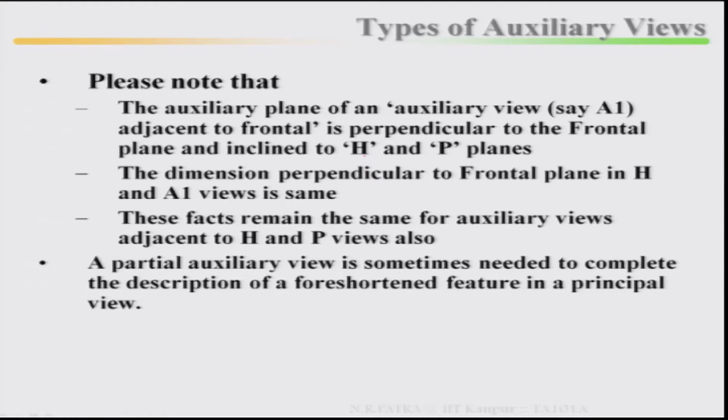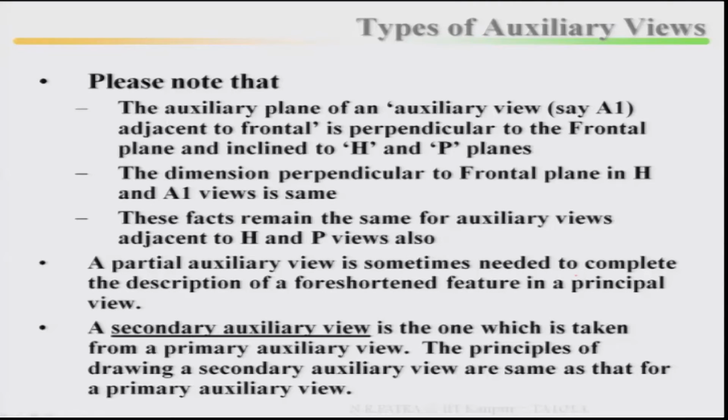A partial auxiliary view is sometimes needed to complete the description of a certain feature in a principal view. Remember this point: not necessarily a complete auxiliary view, a partial auxiliary view is sometimes needed to complete the description of a certain feature in a principal view. A secondary auxiliary view is one which is taken from a primary auxiliary view. The principles of drawing a secondary auxiliary view are the same as those for a primary auxiliary view.